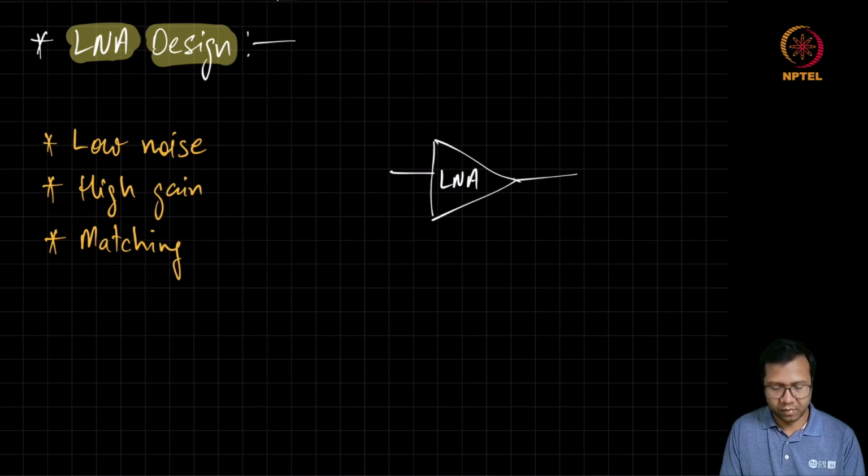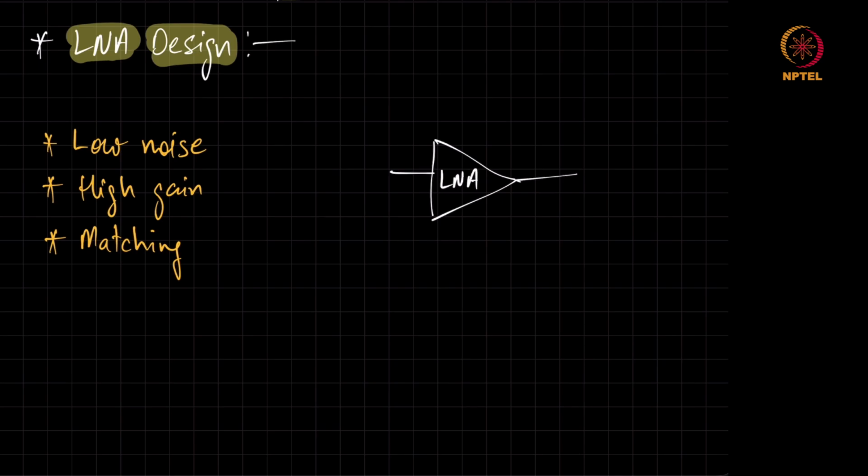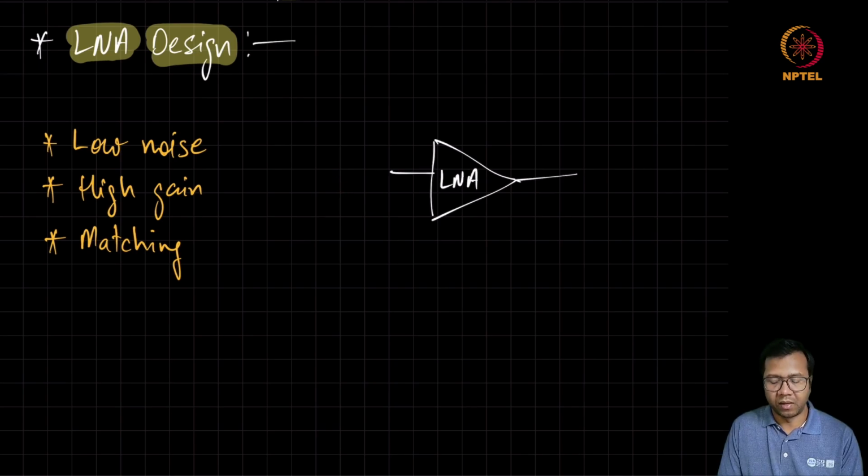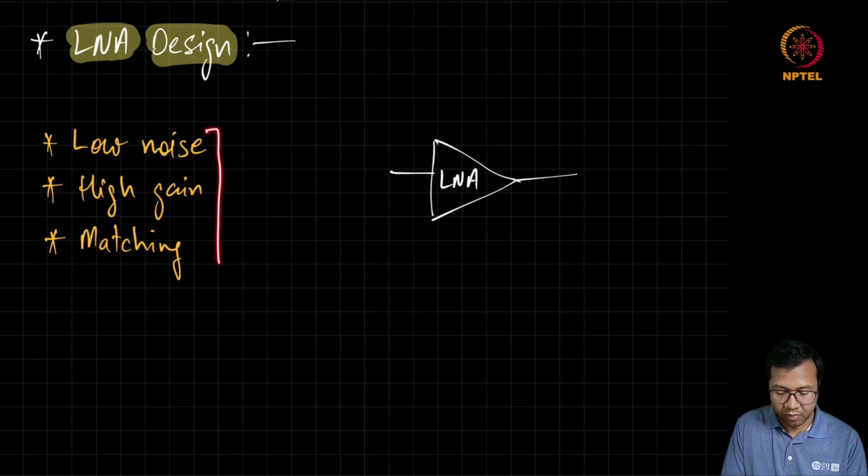While keeping these points in mind, we need to make sure when the LNA is designed, it is also stable. In addition, the LNA should be able to handle out-of-band blockers which are attenuated by the band select filter. Even though attenuated by the band select filter, there can still be significant power. So those out-of-band signals should also be processed by the LNA without causing any nonlinearity. So the linearity and stability are important. In addition to that, we have to make sure the LNA meets the specification for the noise, gain and the matching.